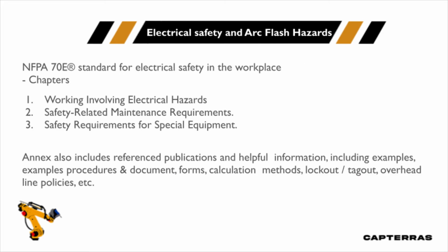So looking at NFPA 70E, the standard for electrical safety in the workplace, the document is a very, very powerful tool that we can use. We're going to take a look at some of the requirements out of Chapter 1, work involving electrical hazards. It's very important we properly maintain our equipment as well. If we have breakers that aren't clearing in time or equipment that's not properly maintained, we're going to have a much greater risk of injury and also possibly much higher hazard levels that we could be exposed to, because our breakers are not clearing fast enough to give us the incident energy that we were assuming in our calculations based on the manufacturer clearing times.